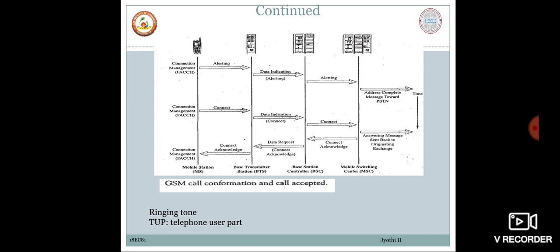One can conceive various scenarios where a GSM mobile has registered in the MSC or the visitor location register in a foreign country, and a call is made to that mobile from the same country that it is now registered in. The home location register is able to present where the mobile is, and directs the call to the serving mobile station or the visitor location register.